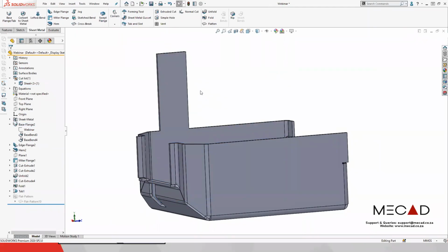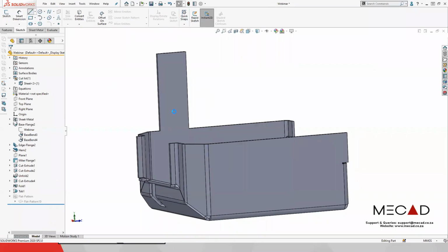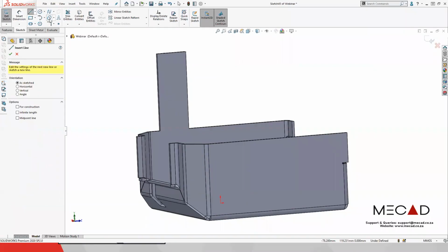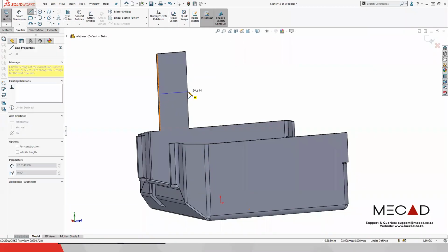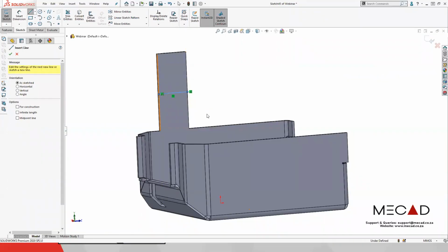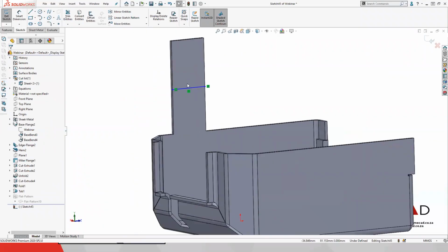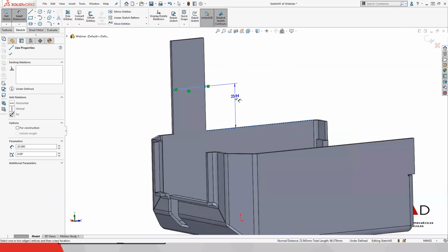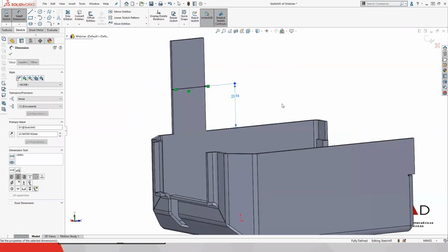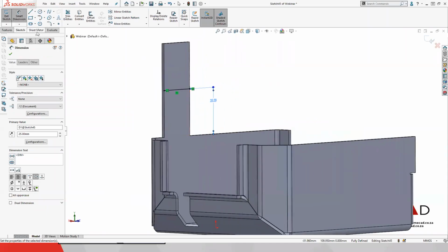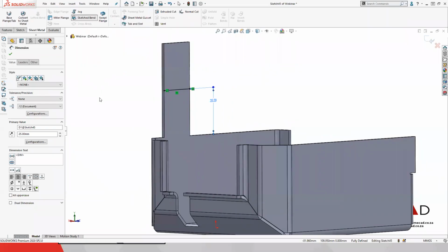Now this tab needs to slot into another component, for example, and we have a specific height we need it from. So I'm going to just create a sketch on the face and draw one line. Okay. We know that that tab at the top that we're going to bend 90 degrees needs to be a height of 25 millimeters from the top. So we need the top face of this bend to be 25 millimeters. So all I do is I draw that line, say sheet metal, sketch bend.